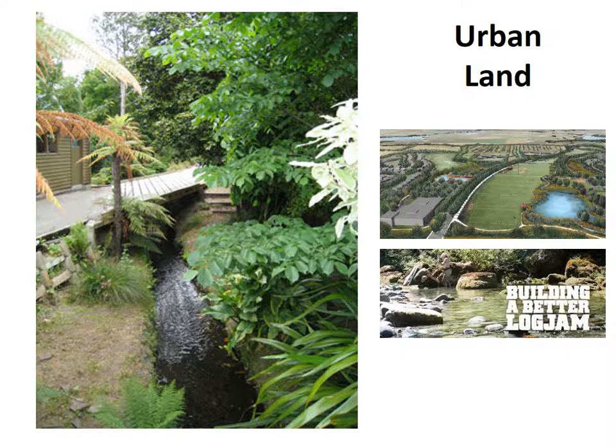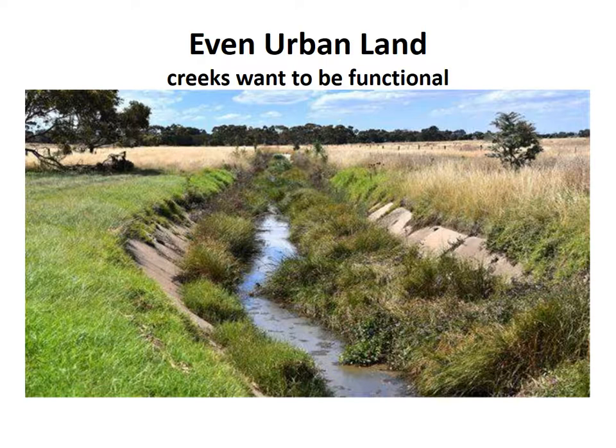Municipalities or subdivisions that desire to minimize damage to creeks and help maintain semi-functional riparian conditions can plan developments to retard runoff and retain wide, well-vegetated riparian areas. The reduction of impervious surfaces, rainwater harvesting, detention storage for stormwater, water gardens, green belts, and other practices are used in some developments to help maintain some natural riparian function. City engineering departments should be taught about the basic processes of riparian function, and especially the role of vegetation and large wood in creeks and riparian areas.